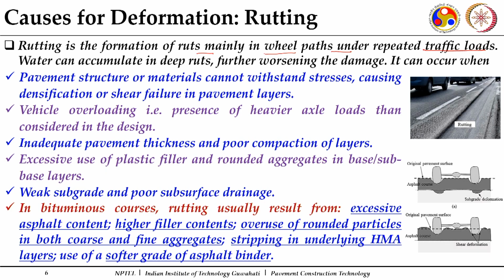And in this particular one, if these ruts accommodate water, or water gets accumulated here and is not able to go off with the help of the camber, then it worsens this particular damage. The factors which contribute towards rutting: first is pavement structures or materials cannot withstand the stresses.